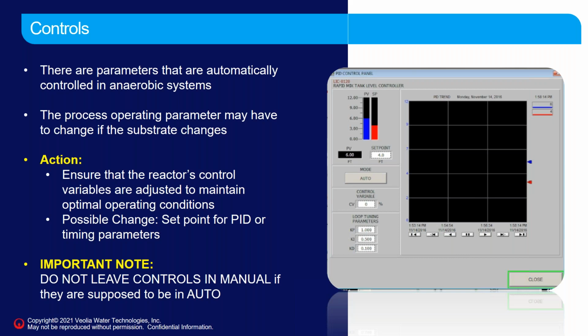Also, oftentimes you're doing some work and you need to run a loop in manual. You have to make sure that you put that back in auto. Any control that is supposed to be in auto has to be in auto and should never be left in manual.